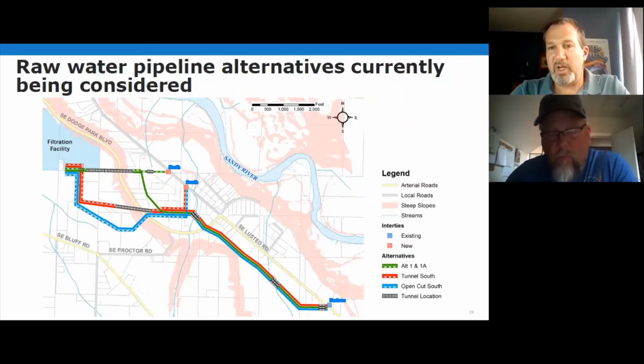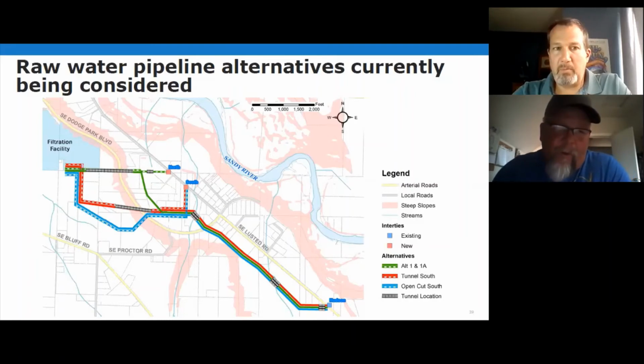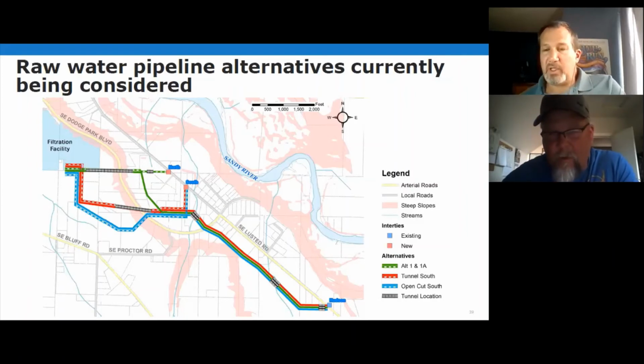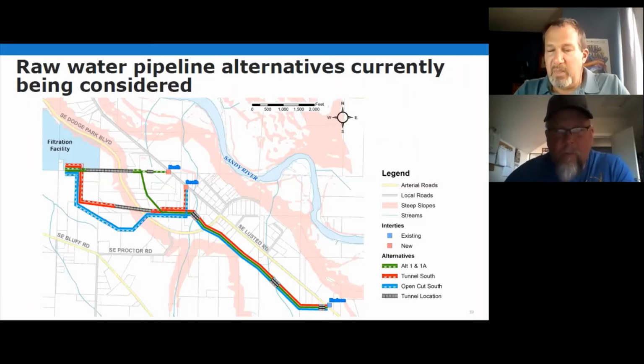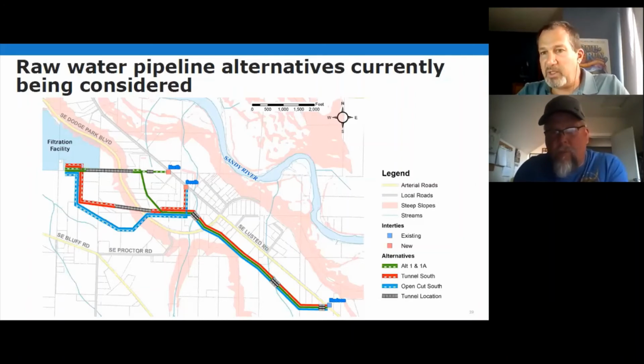So yes, there are trade-offs. You brought up one other thing with the liquefiable soil. It's pretty hard to stabilize, isn't it? Our geotech gave us some designs to look at, and there was some soil mixing that went down below that level, the top 30 feet, I think it was 30 or 40 feet, and they mix in different materials depending on what it is to make that soil stay in place.